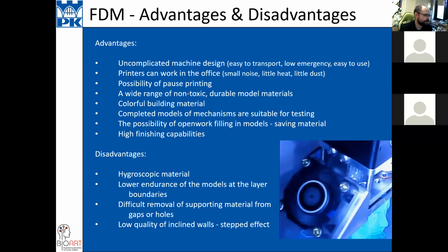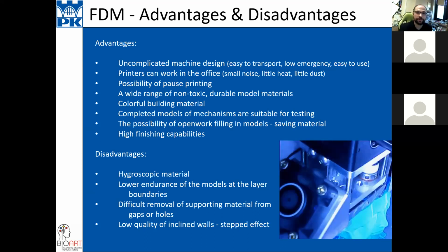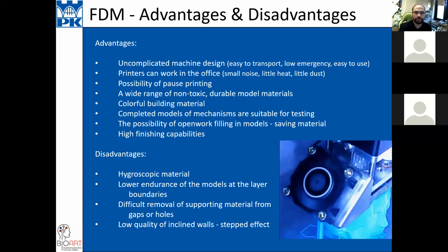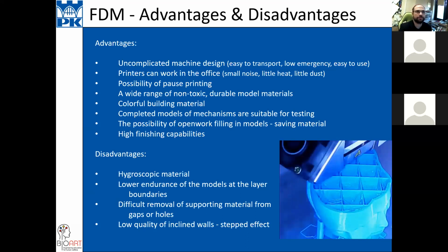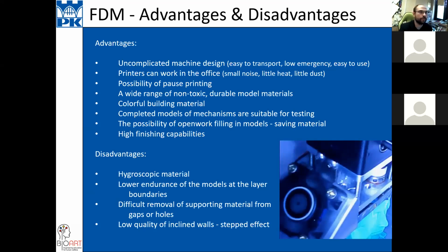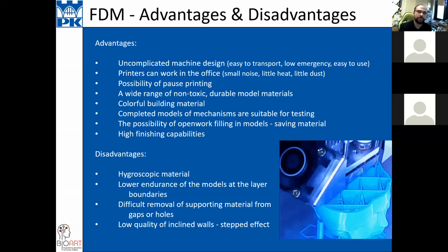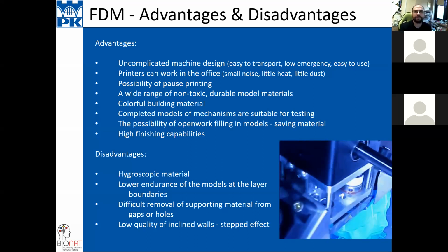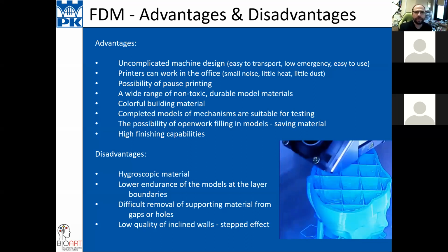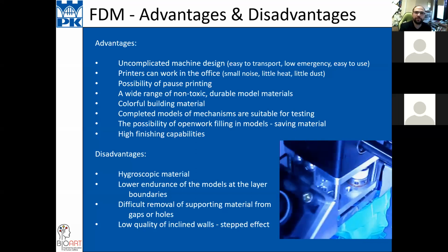In this technique, of course, you can use very different kinds of post-processing. For example, you put the prints into a container with salt, with very small particles of salt. You must grind it before, and when you heat up to 200 degrees Celsius, the structure will be harder.